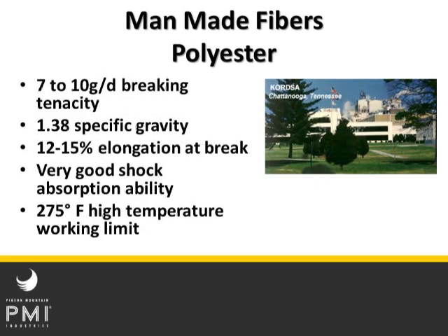Polyester, another really popular fiber now that's come on the market, big in the rescue ropes in the last, I guess, 10 years or so. We've been a little slow to adapt it here at PMI over the years simply because it takes a little bit smarter user to use it, and that's because of the lower elongation at break. I think now that most people know a lot about it and have been working with it, it's a different animal than it was when it first came on the market. So we do offer a number of polyesters ourselves.